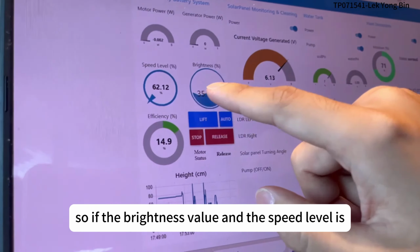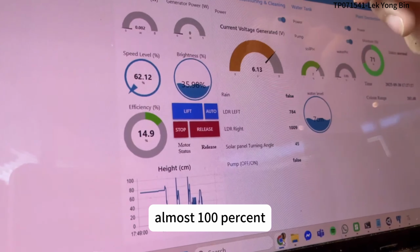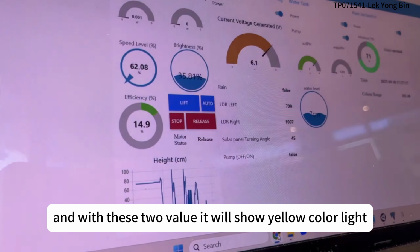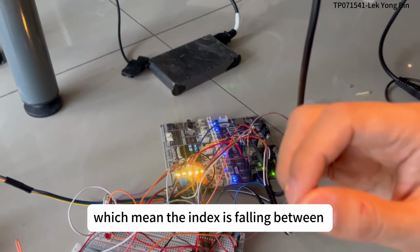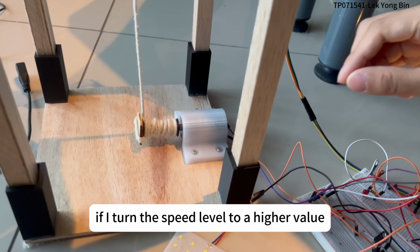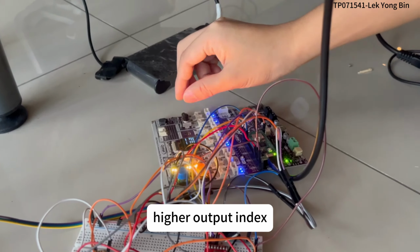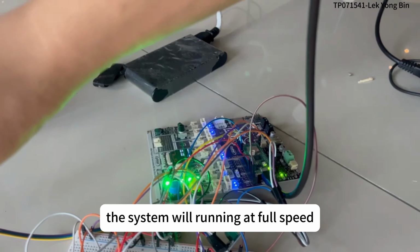If the brightness value and the speed level are almost 100%, then it will show a green color light. And if these two values are lower, it will show a yellow color light. Over here, it gives a yellow color light, which means the index is falling between 0.5 and 0.7, and the motor will be running at a very low speed. If I turn the speed level to a higher value, the fuzzy logic will give a higher output index. So the color will be green and the system will run at full speed.